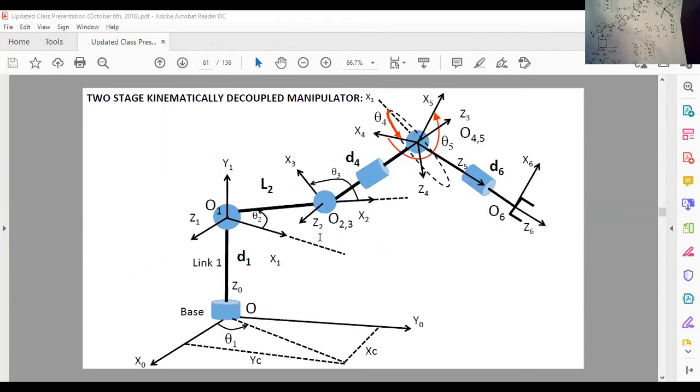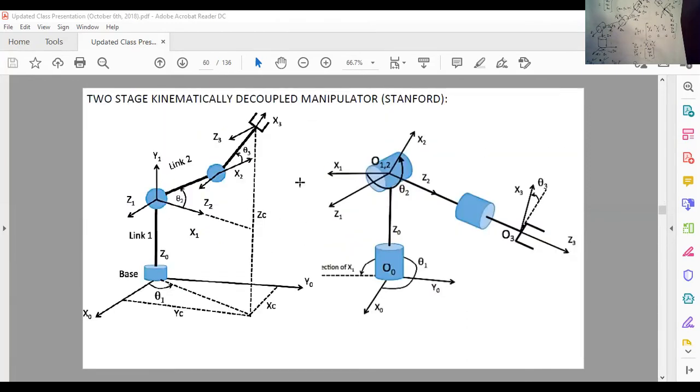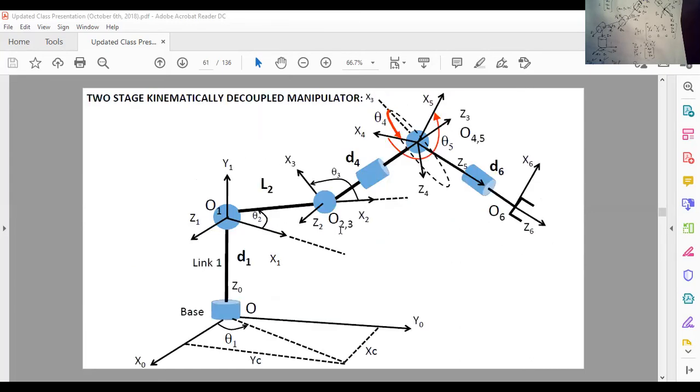Let me quickly go over my presentation. So like I said, a 6-axis manipulator is actually a combination of two, right? The first robot is an XYZ robot, which is only a 3 degrees of freedom robot. And then we attach to it that wrist, and the wrist will enable me to position and orient the tool of the end effector on the robot basically in any position that I want. And this is what we have. We've already explained and went over all of this.